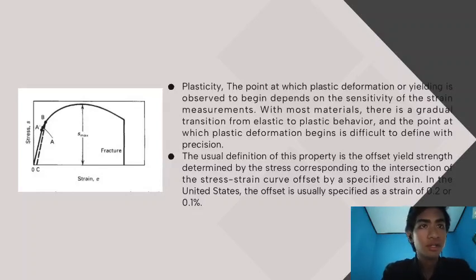In the test of material under uniaxial loading, three criteria of the initiation of yielding have been used. That's the elastic limit, the proportional limit, and the yield strength. With increased sensitivity of strain measurement, the value of the elastic limit is decreased until it equals the true elastic limit determined by microstrain measurement. With the sensitivity of strains typically used in engineering studies,